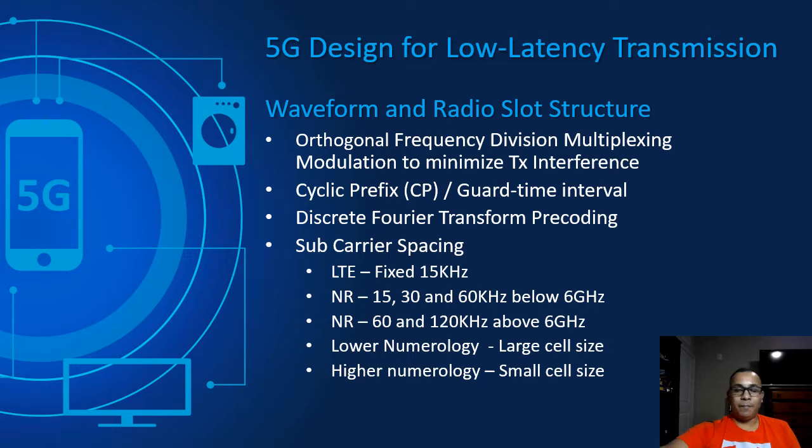Now here, the system is based on orthogonal frequency division multiplexing, which allows minimizing transmission interference. And in this system, a cyclic prefix is implemented, and what that allows is to protect data from adjacent interference.